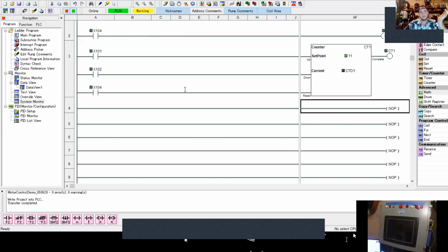But I know, based on looking at the index and looking at my system configuration, that the analog output for the VFD is going to be DF5. That value in memory is what's being interpreted and changed to a physical analog output, a 4 to 20 signal from that card. So that's going to be DF5. So I can just write that into that result field. I don't need to worry about searching and figuring out anymore. I already got that figured out.